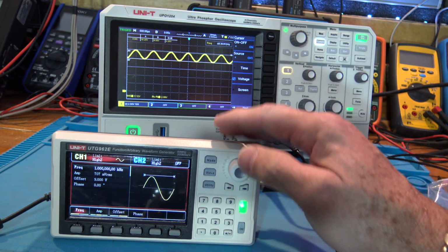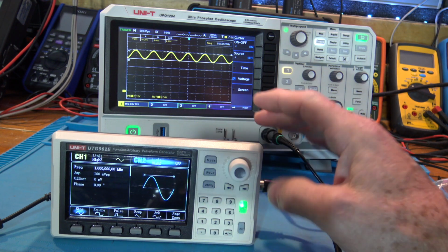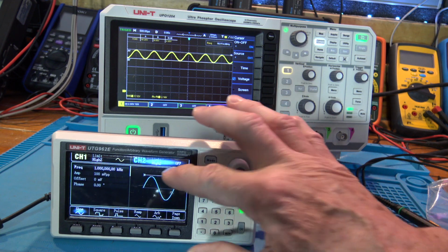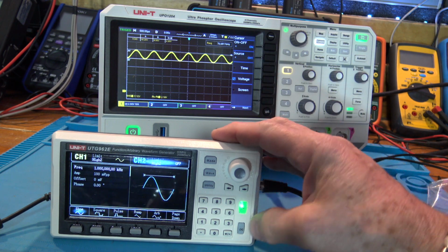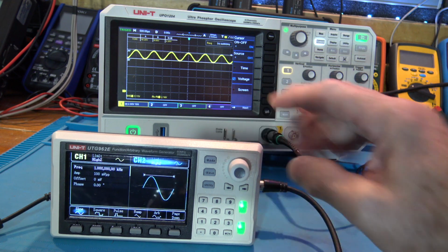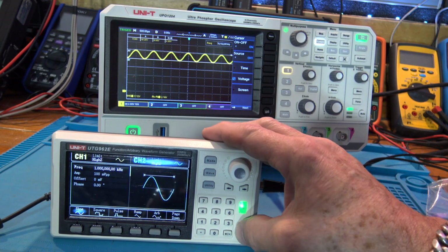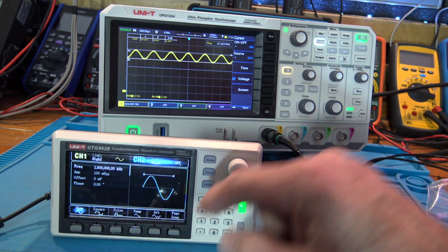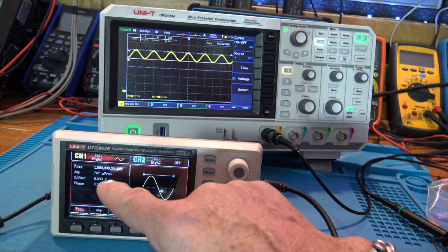For channel 2, I can just come down here and hit this button, and it highlights this. If I go back to channel 1, it highlights that. Channel 2, it highlights this. So now I'm ready to do the same kind of setup on channel 2. Then I can hit the on button to actually put it out of the BNC connector here, okay? So that's how you can do your 2 channels. That's your sine, your square. So let's go back to channel 1, okay?